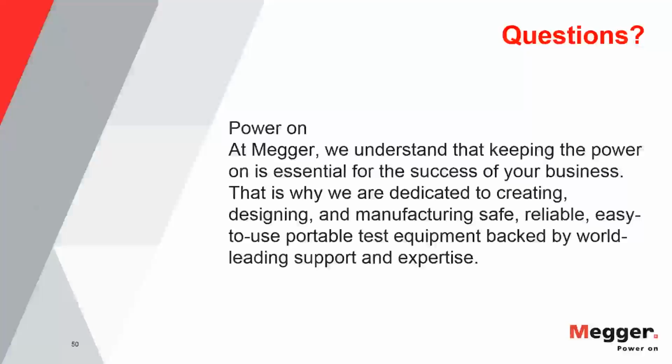So for a commissioning test, when you want to combine all of that, CR and then the DAC. The DAC is, as I said, just the diagnostics, and its high test capacitance comes from the fact that you're just releasing one shot and you take your time charging the cable. It is not a continuous waveform. So sometimes on transmission cables, you charge the cable over 5-10 minutes, and then you release the shot. And of course, if you can take that time with a non-continuous waveform, you get a huge test capacitance out of that. Just to clarify this.